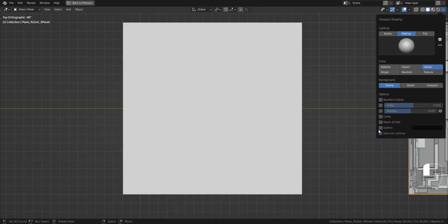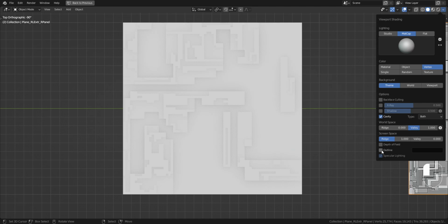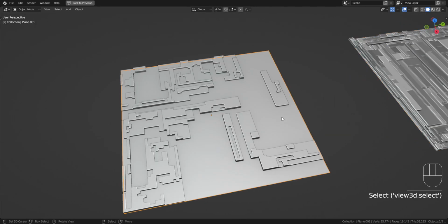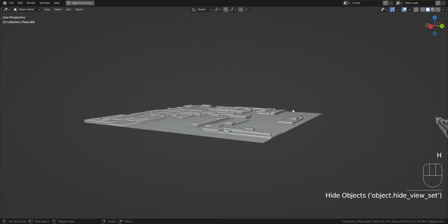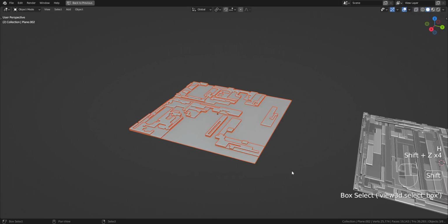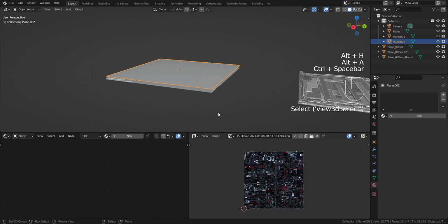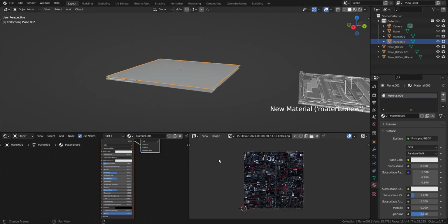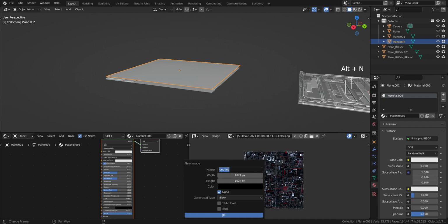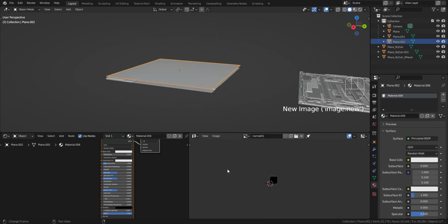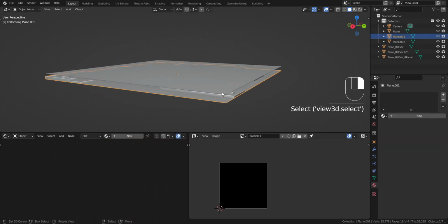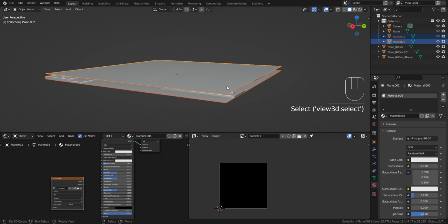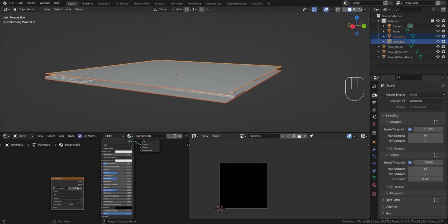So I'm just going to demonstrate. Let's turn on cavity and outline and create our bake material plane. Select these objects, Ctrl J, select this one, new material and new image, normal 01, drag it here and select our design and then our bake mesh, bake to mesh.